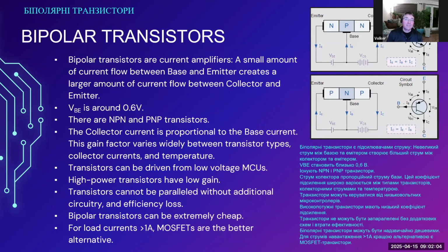If that event happens, then a bipolar transistor can still be used to switch some external devices, to switch some external event that has to happen. It is very difficult to find a standalone MOSFET that can act at these low voltages. A bipolar junction transistor can.